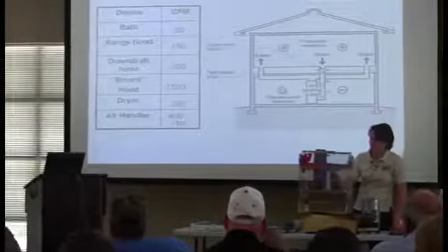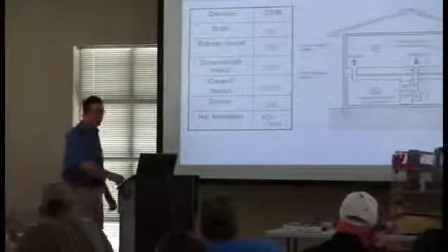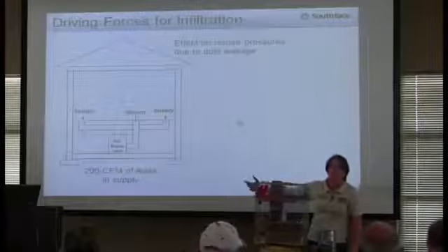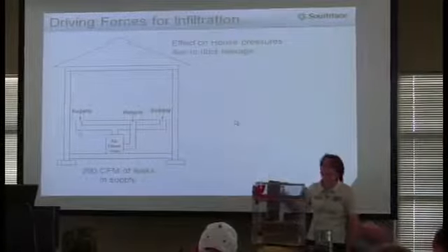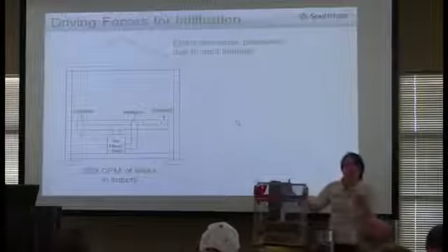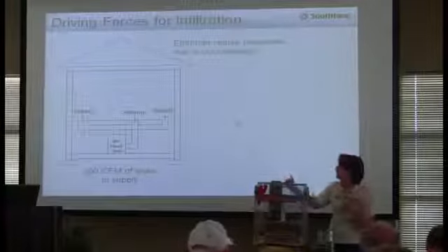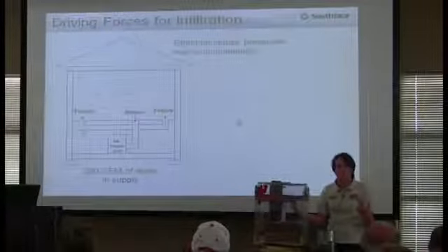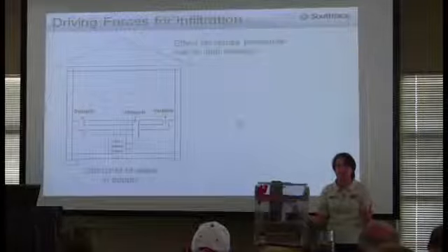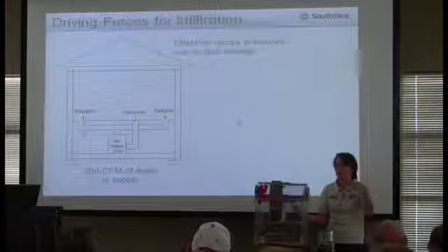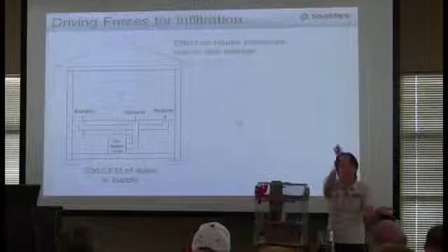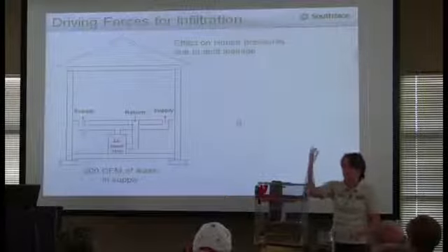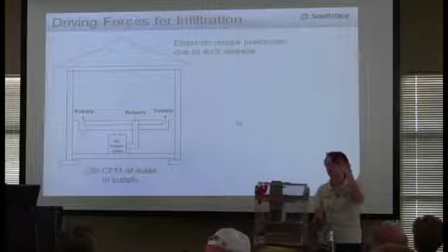Why don't you tell us really quickly about duct leakage? Let's go to the next slide. All right, so in this example, we're going to simulate some supply leakage. If we have a 2.5 ton system, and that's what our air handler is, we are going to be pulling 1,000 CFM from the house, right? So if we're pulling 1,000 CFM from the house, 200's leaving to the crawl space, how much is actually getting back into the house? 800. All right, so if we're pulling out 1,000 and only giving the house 800,